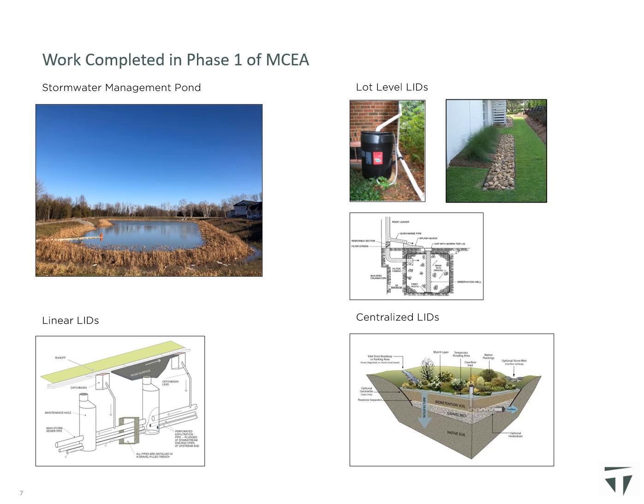Low-impact development measures can be classified into 3 categories: lot-level LIDs such as rain barrels, rain gardens, and soak-away pits, linear LIDs such as perforated pipe systems installed below storm sewers, and infiltration trenches installed below roadside ditches, and centralized LIDs such as bioretention facilities or other infiltration galleries.